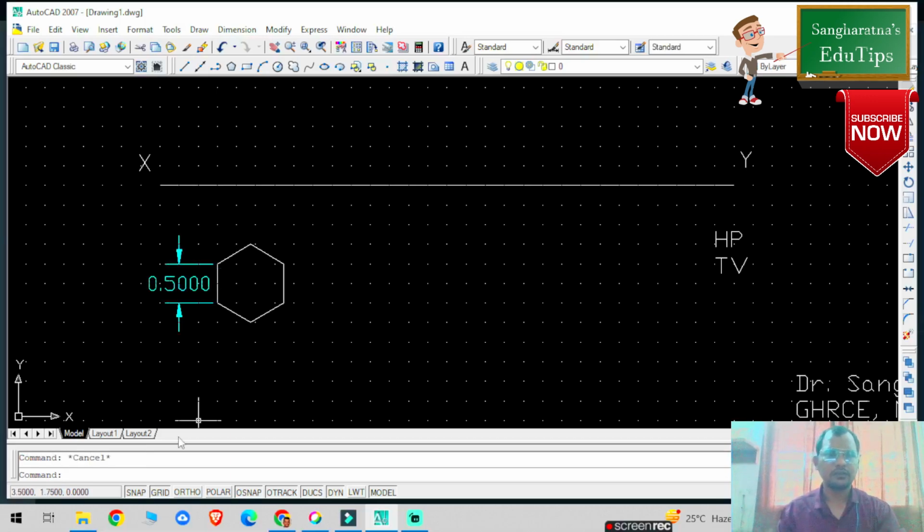Now you need to give the text command. Select any point on the screen, specify height 0.2, rotation angle 0, and give the naming. So this is my point A, this is my point B, this is my point C, this is my point D, this is my point E, and this is my point F.